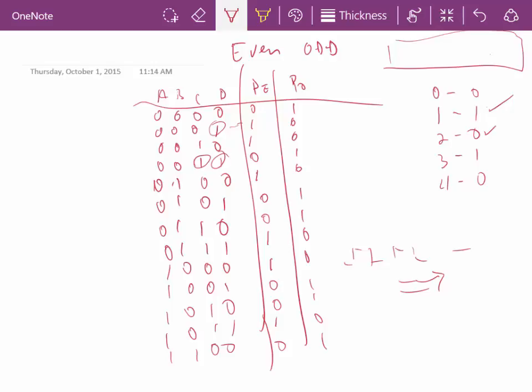Now, parity is based on statistical analysis, which we're not going to go through. This is not a course on statistics. But statistically, the odds of 2 bits being wrong in the same byte is very, very small. The odds of 1 byte being wrong is relatively significant, but having 2 errors in the same byte is relatively small. So in that case, we catch about 99% of all errors by using just simple parity checking. Parity checking has been around ever since the days of digital communications.